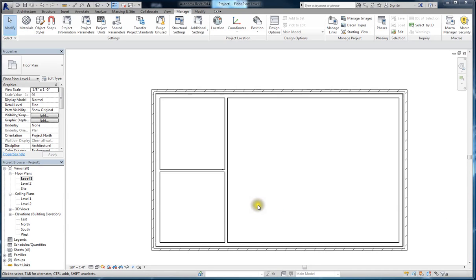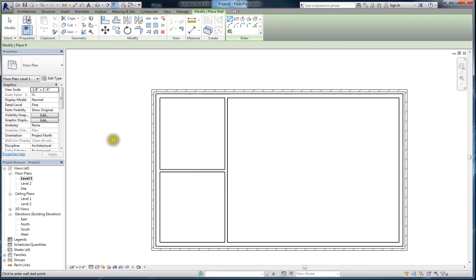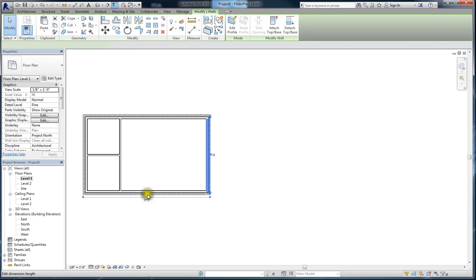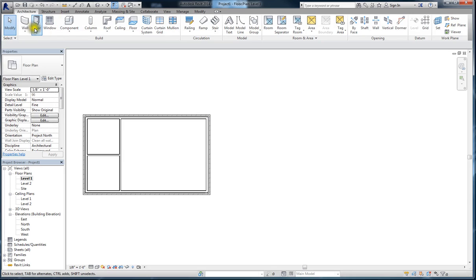We continue with this video, and we were talking about how to input or how to draw the walls. So the first thing we did was we went back to the walls, and we're just drawing by dragging and visually seeing what the dimension is, and then we would select the wall that we wanted to move and change the temporary dimension. That was one way. Another way is to do this.